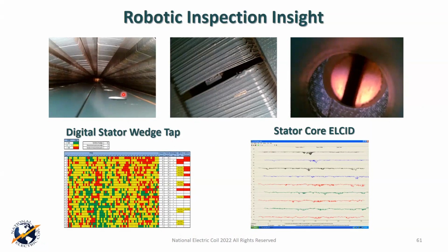This is just a representative sample. I'm not terribly concerned by this picture, but you've got a little bit of flaring laminations, and this is an example of the upward-facing camera looking at the stator core, all right? And this flaring is not something I'd be tremendously worried about, but if I saw major dings from foreign material, or I saw major rust that I thought might be causing interlaminar damage, the robot can help pick that out for you.